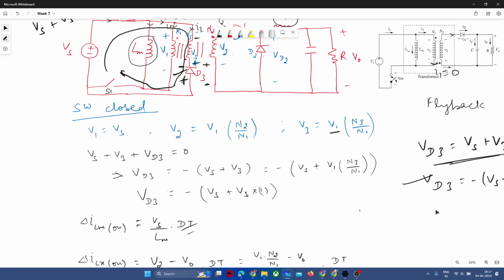BM, Tesla, I am talking about. But we are using here only 0.25 or something. Yes, in power electronics we do not use more; it will be limited to 1 or 0.5. And in motors, you can go up to 2.5 Tesla or 2.4 Tesla. So it is limited. But there is no material, sir, that is also achieved in advanced material like cobalt steel, right?